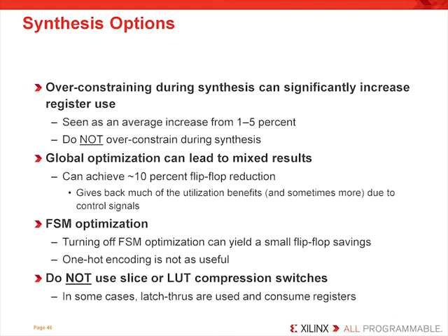Over-constraining typically makes designs bigger and increases the number of registers used, since synthesis tools tend to replicate logic to decrease fan-out on timing-critical paths. Typically, this increases register usage by anywhere from 1 to 5%.